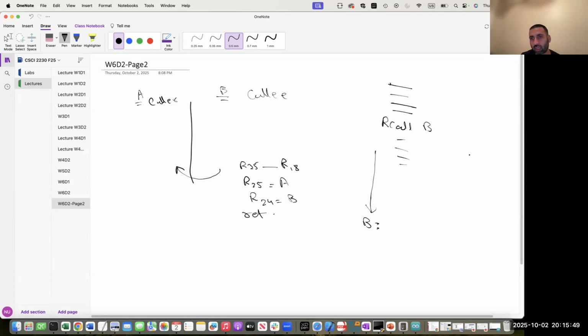it depends upon the value of your 12 bits, right? So if the value is positive, it means it will be forward as compared to PC plus one. So you will be taking a forward jump. And if the value of these 12 bits or the operand bits is negative, remember we are interpreting it as a signed number, so you will be jumping back.